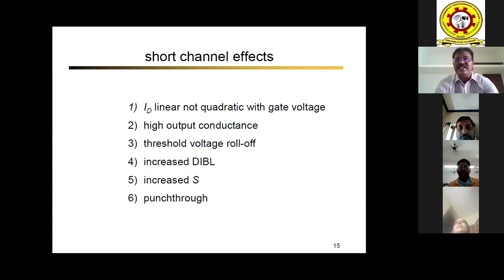At a certain level, that is your threshold level, when the gate voltage comes to your threshold level, this energy barrier is automatically nullified and your carrier actually moves from source to the drain. This is what actually our intention is while designing any MOSFET.